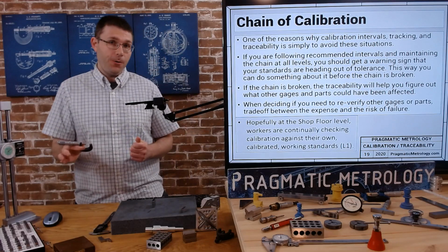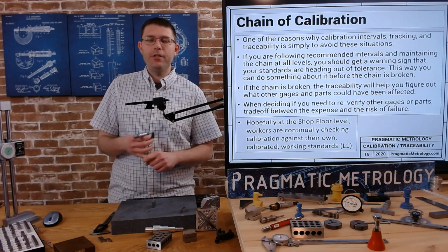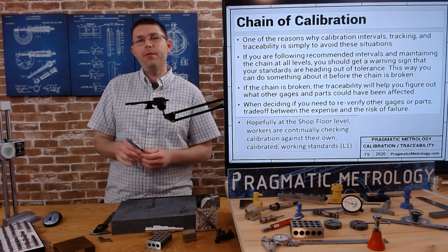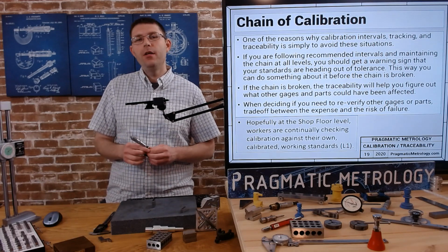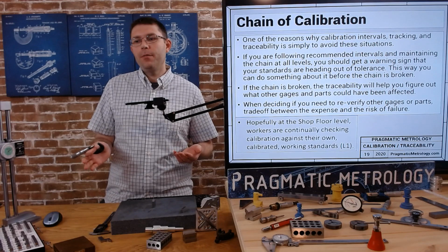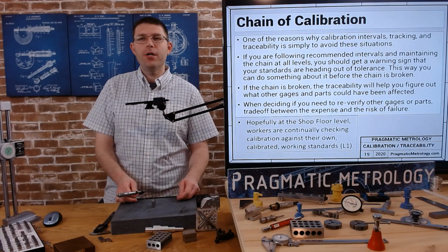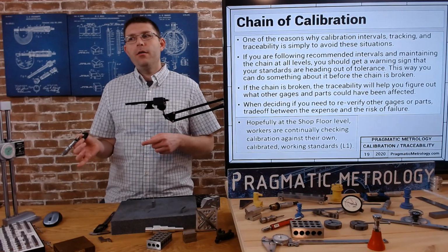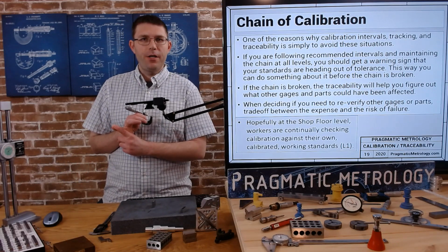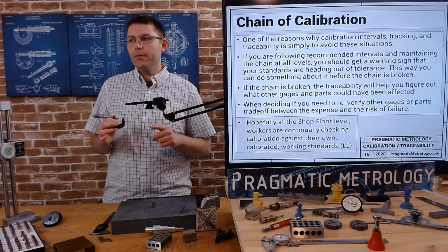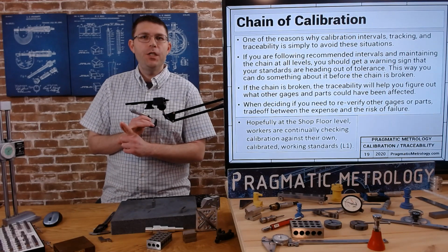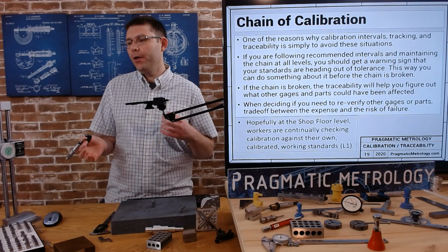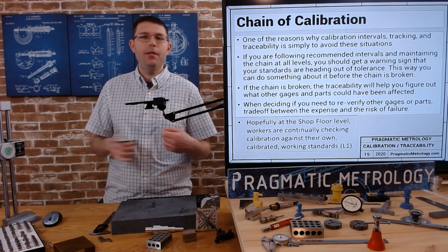measured with this micrometer. You discuss their tolerances. You discuss any measurement data that you had and see if some of it goes out of tolerance. And then sometimes you say, okay, yeah, we gotta remeasure these parts with a calibrated gauge. Other times you say, well, the risk is low. If there's a problem, final assembly will catch it before the customer. Or if there's a problem, final assembly can adjust, make a correction that is acceptable for us. Or they'll screen it. Final assembly will just screen out the bad ones.